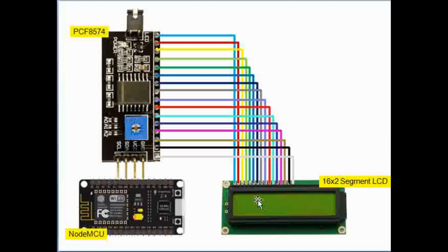In case you are using a breadboard, it's a straightforward connection. If you see, the connectivity from the NodeMCU is so minimized that you need not use all these pins. You just need a total of 2 pins, that's it, I2C, apart from the voltage and the ground. So the number of digital pins that are required is only 2. So simple, right? 16, and we have only 2 here. Wow, awesome. So let us continue our discussion.